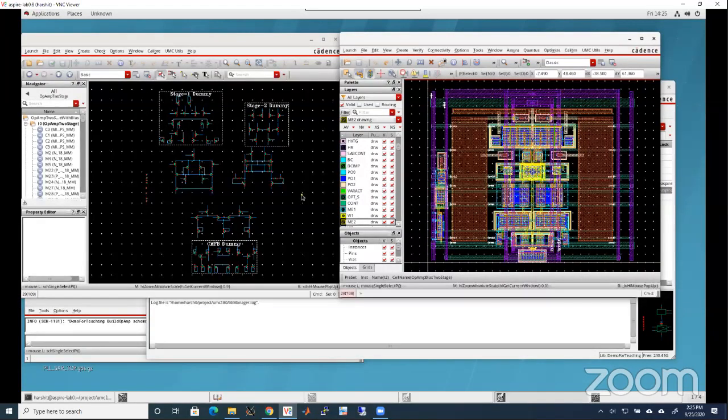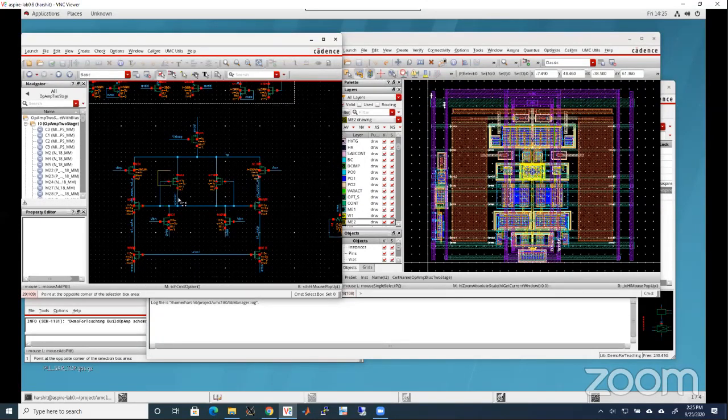Because to do that layout right in front of you, it takes quite some time. So I showed that initially you do the half circuit and instantiate the devices. Here, this bias transistor, cascode bias, we had 2 fingers, luckily an even number of fingers, so we could split it up into half circuit, right? But in the other case, we did not have it, so we had to do a separate one. Both half circuits did not contain the bias circuit. Okay. Any questions?